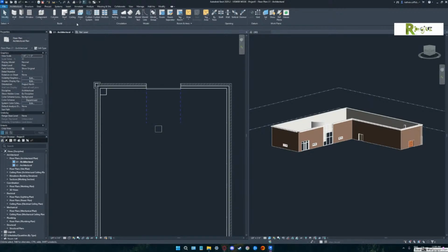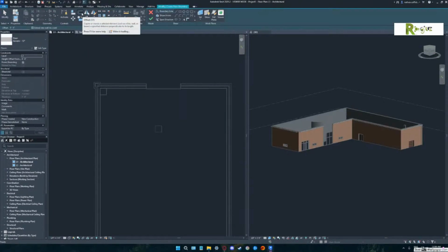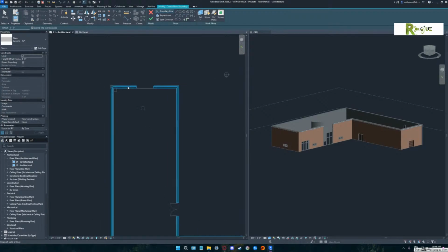All right. So if you go to the floor command, now when you go out, you can draw lines. You see how it says boundary line? That's going to let you select the walls. So go down and you see how you select the walls, and you want to be closer to the inside. And you could actually hit tab right now, and that'll select all your walls.